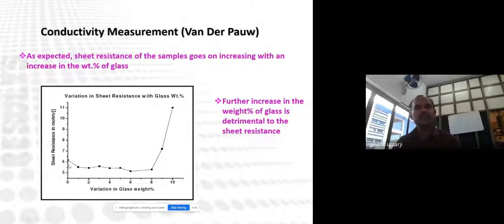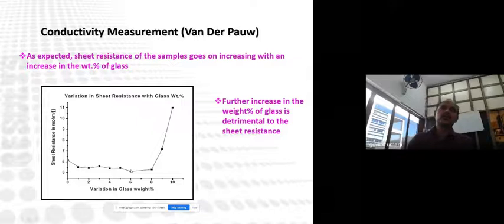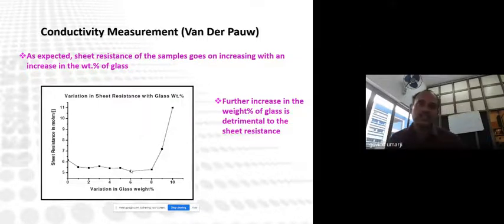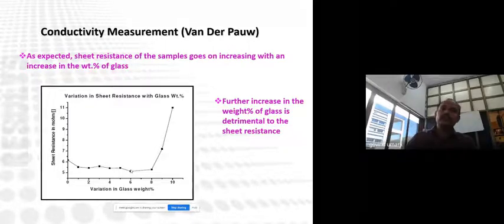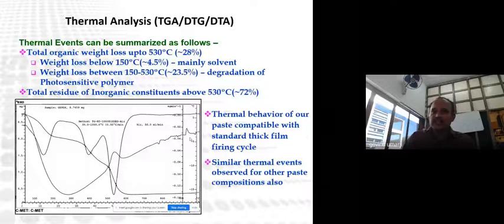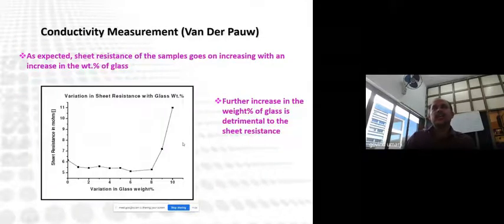But as we increase the glass percent, there is good glass-assisted floating of the silver, and once the glass cools, the silver grown particles, which we can say are flakes because they melt, here we can see 960 degrees Celsius is the typical melting point of silver, and at around 850 degrees Celsius it gets softer and forms a flake-like structure.